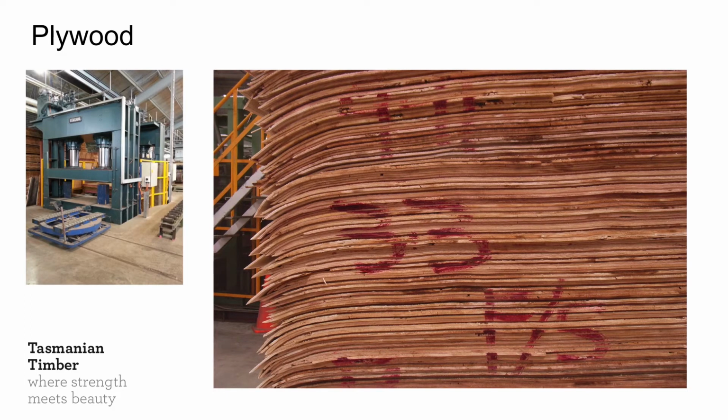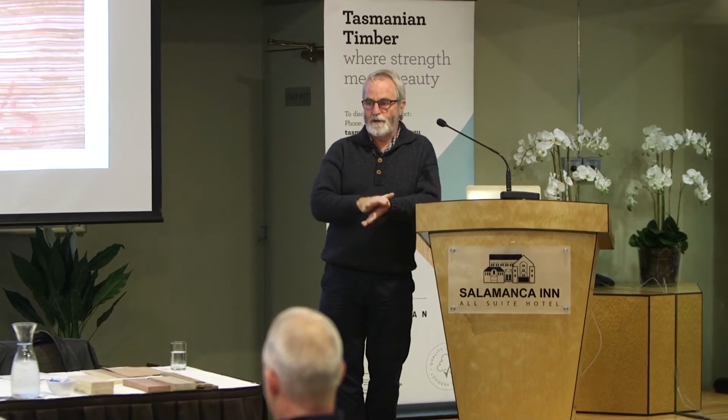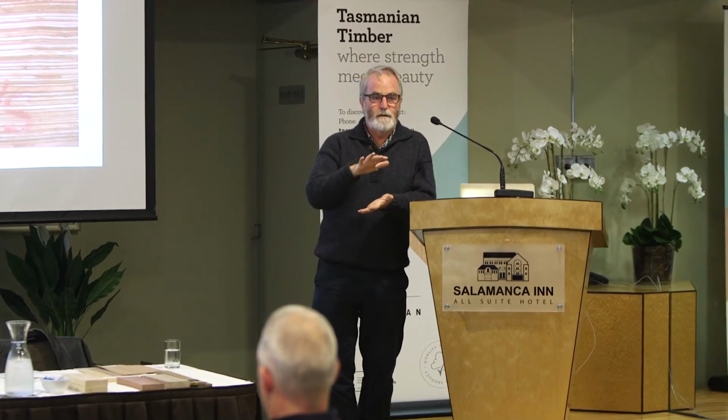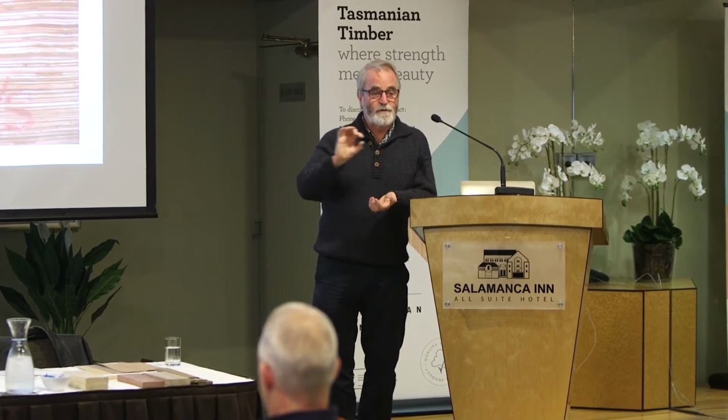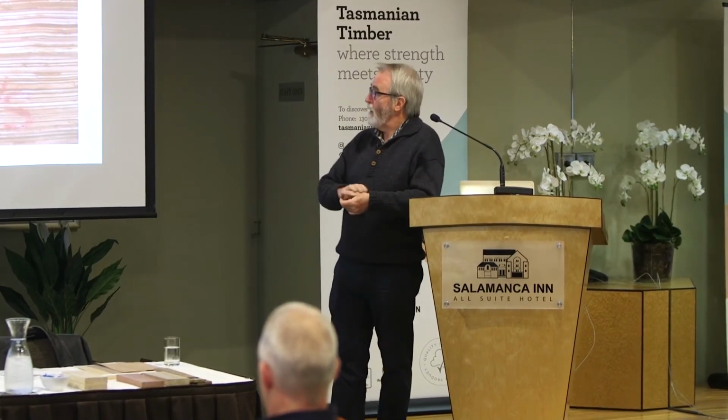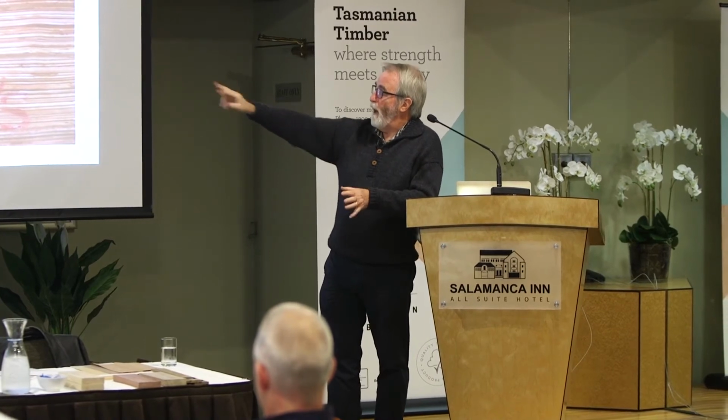You've then got to put glue on, press it. You press it once to get it to effectively the right shape and size, and that's what you do in this one on the left. Then you put it in another press that puts in a lot of extra pressure, heat, and time, and then you end up with the solid plywood product. So that's one of the products that's now available.